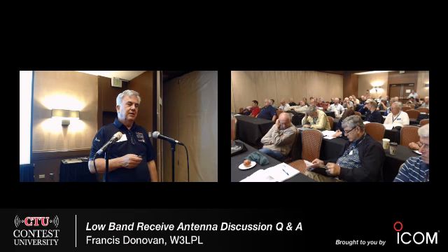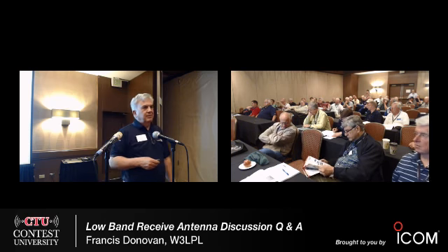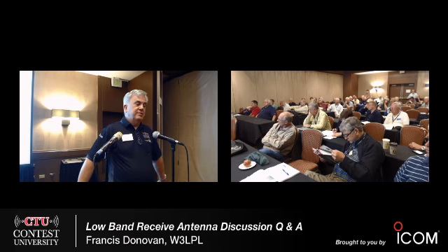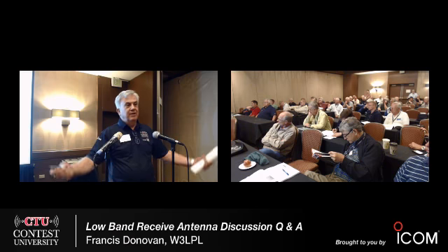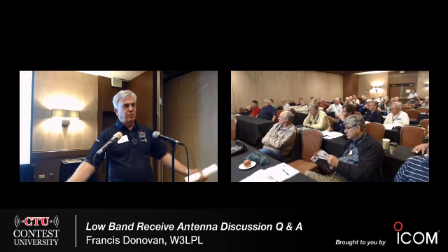Yes? Bill, KC4O. Frank, I'm intrigued by this vertical wire thing. I've got a Beverage that just happens to be toward the northeast where there is a power pole. It's always been noisy. It's been greater than anything I've had receiving. How much would I need to move it horizontally, parallel, if you will? A couple hundred feet would do it, you think? How long is the Beverage? Yeah, it's on 160 meters. That's a 540-foot Beverage, which I used as my primary receiving antenna on 160 for 20 years.